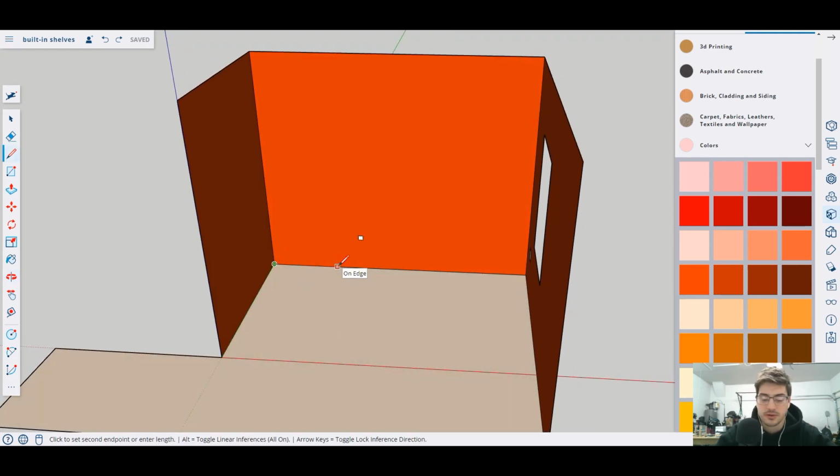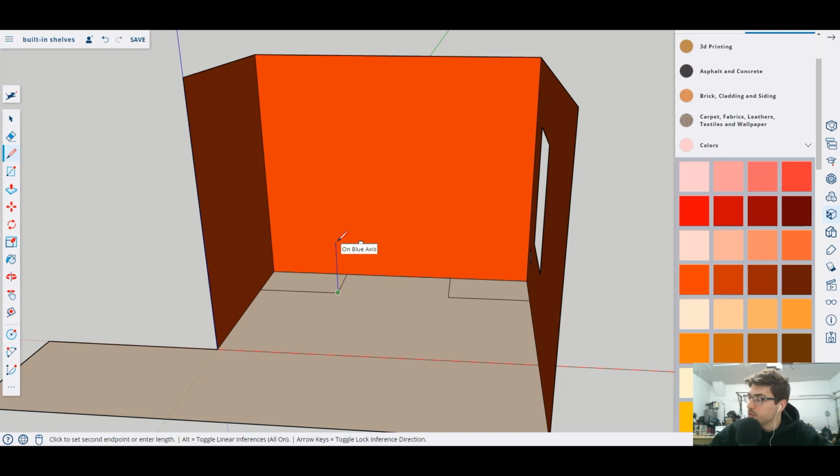So just if you're wondering where any of these dimensions come from, that's kind of where. But if you have some different thing you want to use, then go ahead and do that. So just to recap though, those are 42.5 inches wide. And then what we're actually going to do is build them out from the wall a little bit because standard desk depth is 24 inches. So we're going to make these rectangles that are from both sides 42.5 inches wide and then 24 inches deep because that's a really easy to use standard desk size. And we're going to use the normal desk height of like 32 inches. So just for this model, we'll say 32 inches, okay?